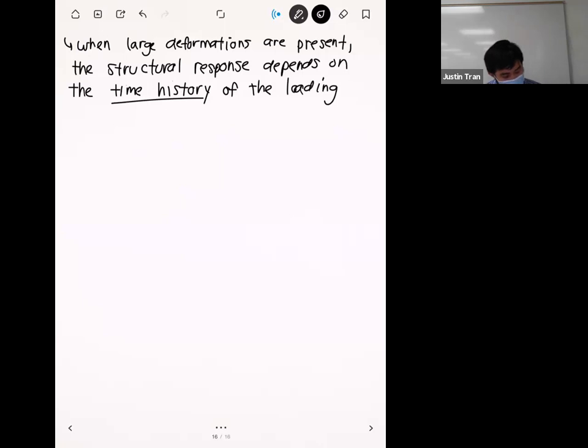And so, we don't often think of time history when we're doing static situations, right? And so when we're doing a static simulation, we have this impression that we start with the structure at rest and then we apply the load and then it instantaneously deforms into what it needs to be, okay? But in reality, when we apply loads on a structure, all the deformation usually doesn't happen right away, right?